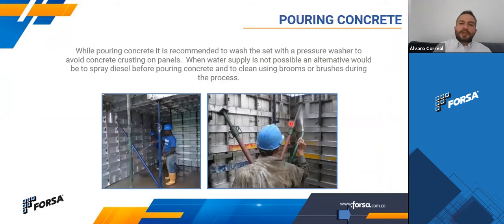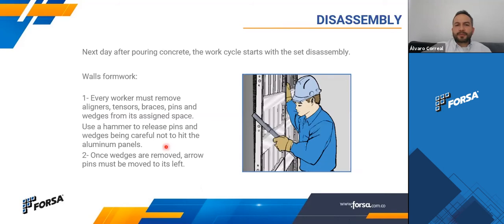Inside the formwork, it's recommended to have someone washing the formwork with pressurized water if possible. Sometimes a bit of concrete gets inside, so you can wash the forms and it won't get stuck into the formworks. And that's it. You finish, you level your slab, and everything is ready.